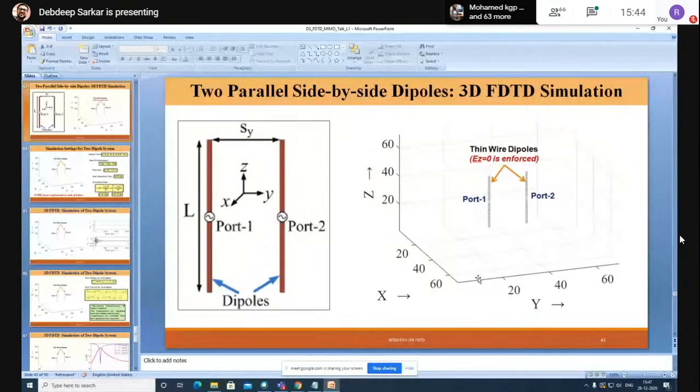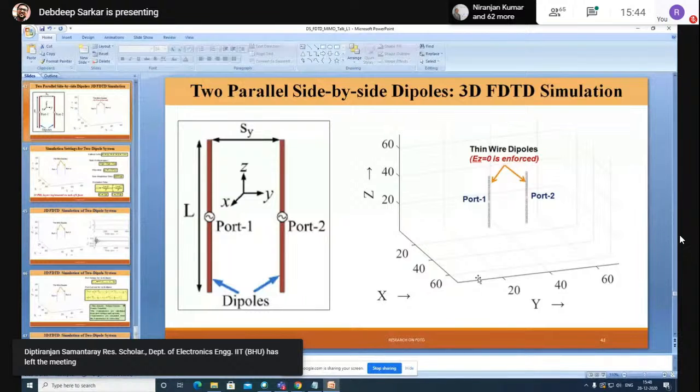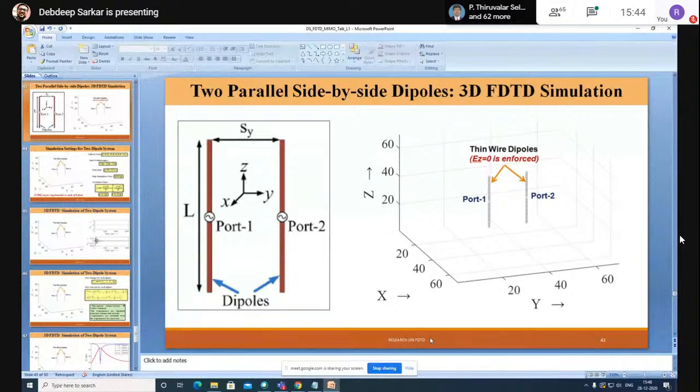Your memory requirement will be very high and a lot of space will be used. But again, you will do the proper meshing, and that will affect the calculated S parameters. The result from the discrete simulation might be closer to whatever you get from the experiment. So meshing is definitely very important. And how you mesh your antenna matters. Sometimes you might need adaptive meshing also. Some regions might need a finer mesh, some regions a coarser mesh. All these things are there, so it definitely matters.